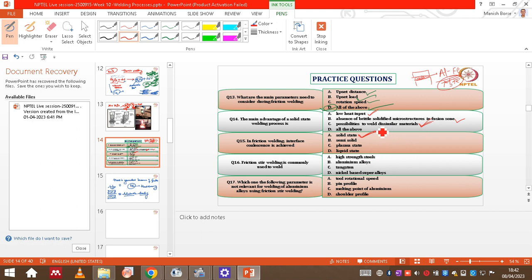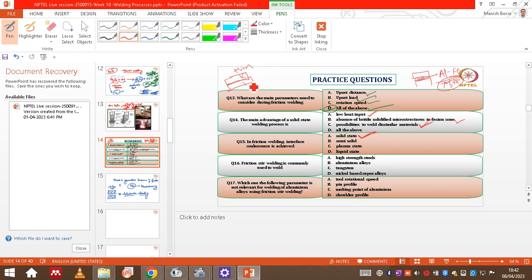We have also seen that in resistance welding, if we use different materials, say one material has high thermal conductivity and the other has low thermal conductivity, then obviously heat will be contained in the low thermal conductivity material, and the nugget size or area will be higher in the lower plate compared to the top plate, right?